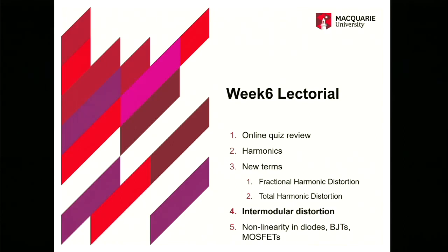So another term which is very close to what we're going to learn in mixers is intermodulation distortion. Everything we talked about till now is a nonlinear system where we give an input and check the output. Like a diode that is DC biased, we give an input Vi, it passes through this nonlinear system and comes out as output. Because of the nonlinearity in the diode, we find extra components in the output. That's what we looked at.